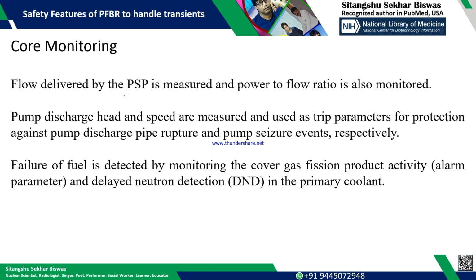The flow delivered by the primary coolant pump is also measured, and the power to flow ratio is always monitored, that means how the enthalpy is evacuated through mass flow. The pump discharge head and the speeds are measured and used as trip parameters for protection against pump discharge pipe rupture, and if the pump seizes or any other such abnormal conditions.